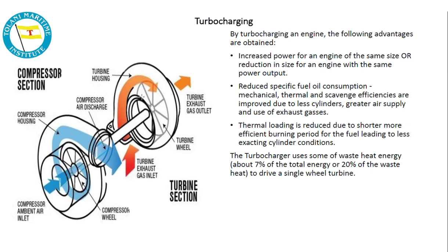Now you see here, we'll go through this text. Increased power of an engine of the same size, or reduction in the size of an engine with the same power output. Reduced specific fuel oil consumption. Mechanical, thermal and scavenge efficiencies are improved due to less cylinder loading, greater air supply and use of exhaust gases.